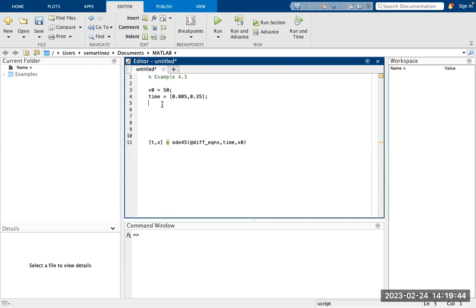One thing that we can do here is options, and you don't have to, but if you want to, MaxStep 1e-4. So that's the biggest value of that h that we're taking every step.